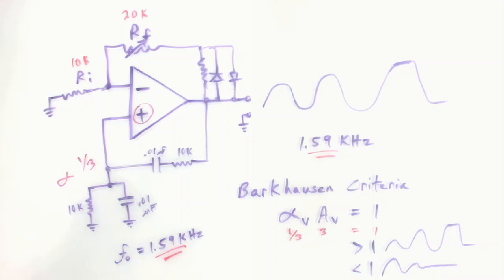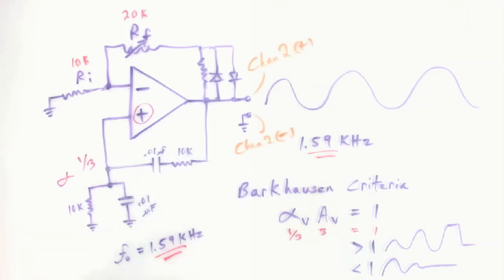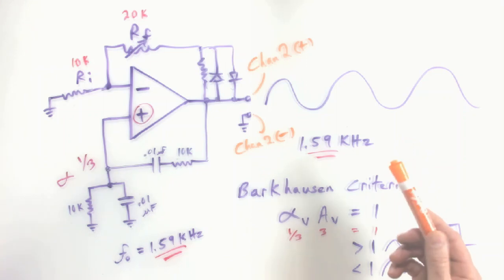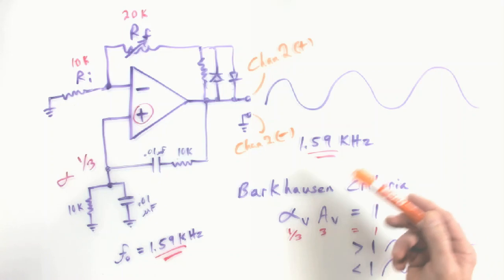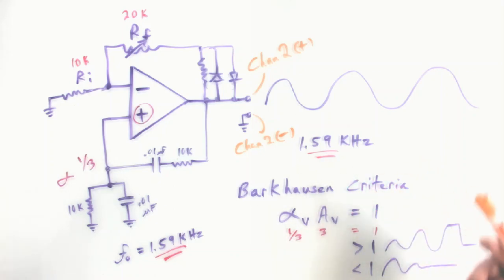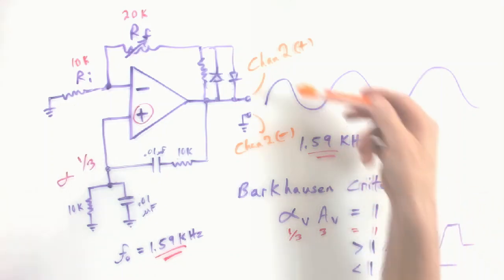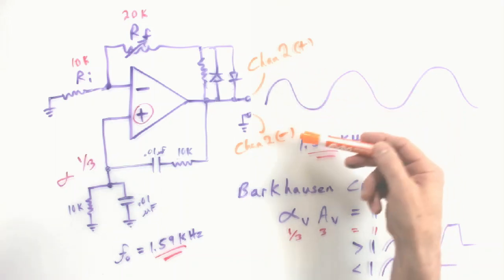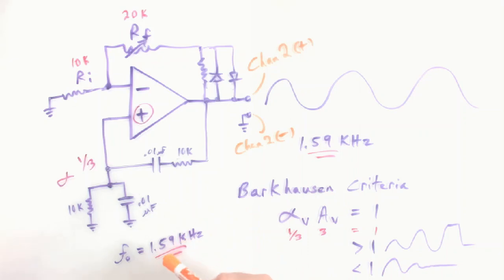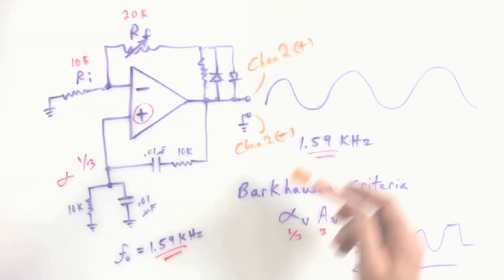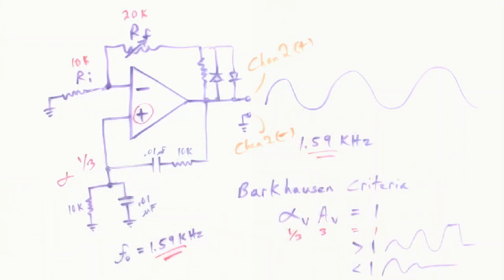So lots of ways to cook up a feedback oscillator. And again, just as a reminder, you only need one scope channel for this circuit. You'll get it built, powered up. If you do get it to oscillate and you want to see that, we've been using channel 2 to monitor the output, so that's why I put channel 2 here. You might have channel 2 on your output. That's it. Don't go looking for a place to put channel 1. There is no input to monitor. We're not putting something in from the wave generator. We're generating a wave. So again, just that reminder. Just one scope channel is all you need to have a look at this thing.